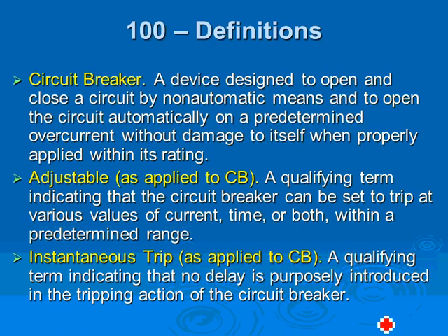There are adjustable circuit breakers, and there are instantaneous trip circuit breakers. Circuit breakers in general are devices that you can manually grab and use as a switch, turning things on and off. As a matter of fact, we sometimes use them as switches, because that is cheaper. Under normal operating conditions, you can use them as a switch. Under abnormal operating conditions, such as a short circuit or ground fault, they work automatically to trip when they reach their tripping value. That's their job.